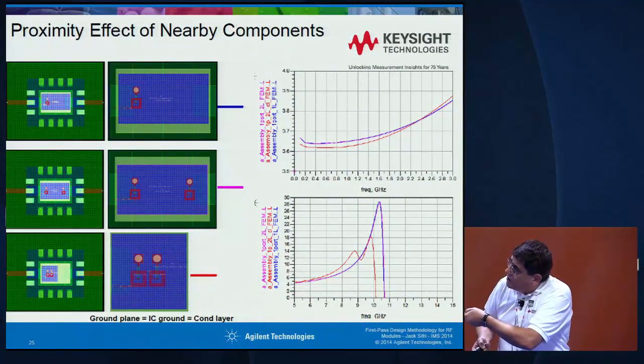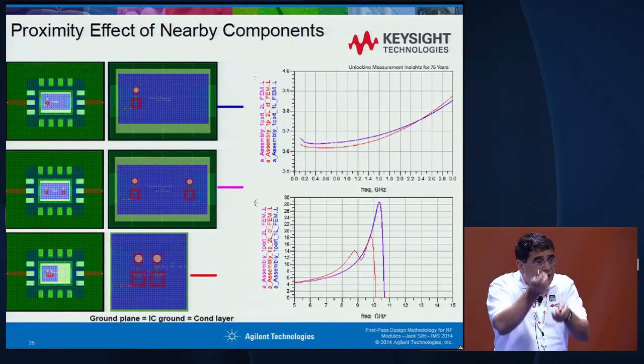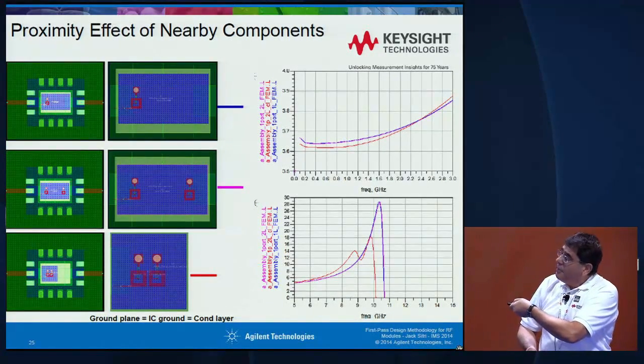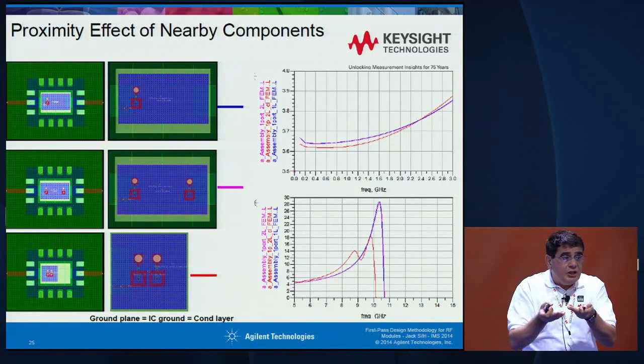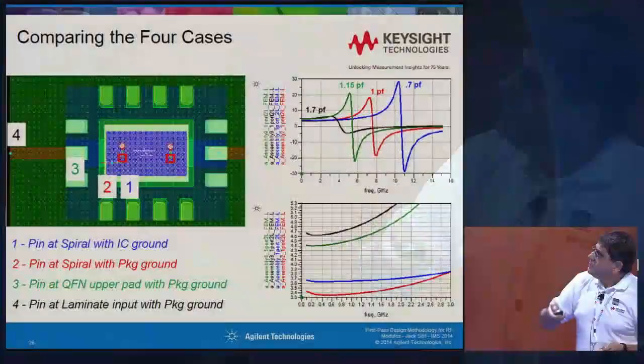It is the capacitive coupling between the two inductors and the capacitive coupling in the substrate. Those two, when I vary them, I get the double humps. Easily it shows up. It's not an inductive coupling. It is a capacitive coupling mainly. So there is a lot of capacitance, and I have the results on my computer, but it just takes too long to show.